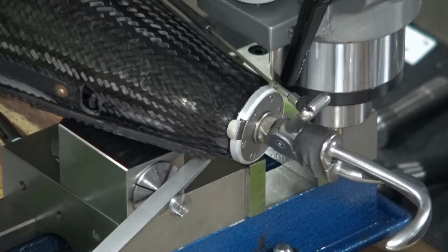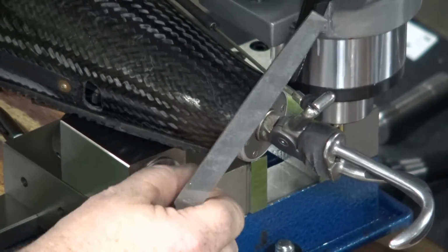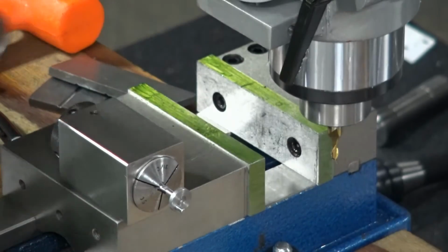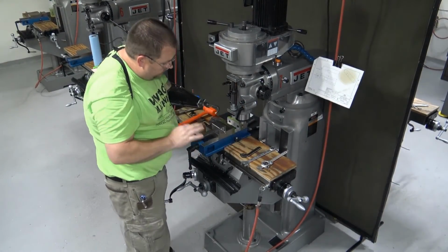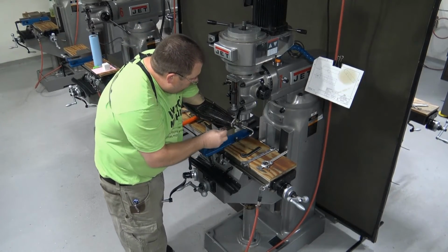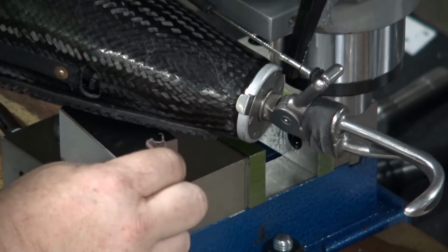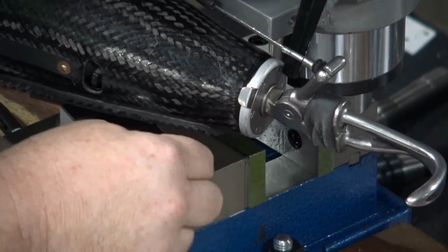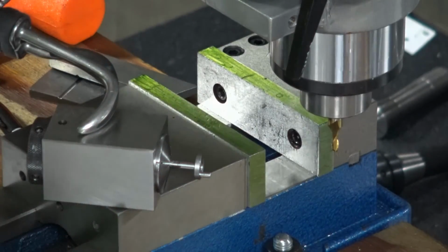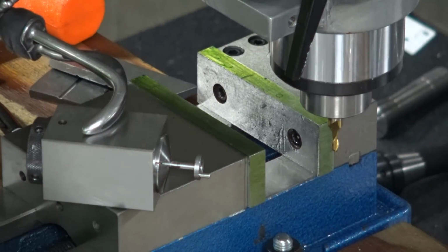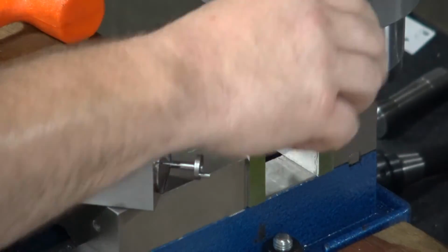because we want our flywheel to slide real nice onto that shaft. Now I'm not putting a lot of pressure on it because I don't want to file little flats on it. It was just enough to kind of skate over that material. And now we'll take our emery cloth best we can. And I believe you can see that. There's my flat. I feel like I've done a pretty good job of that.